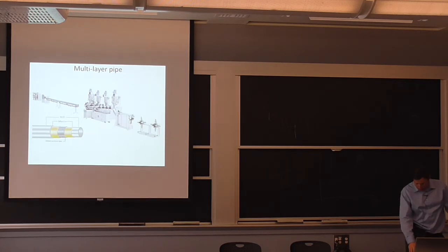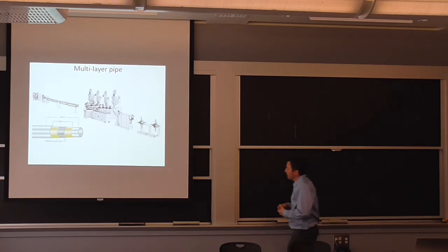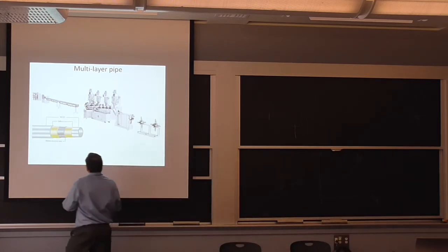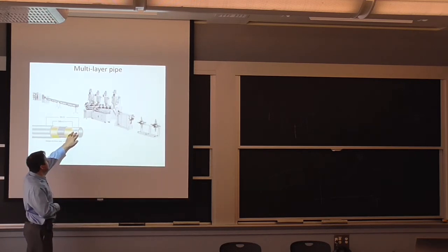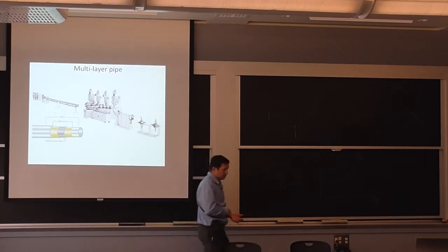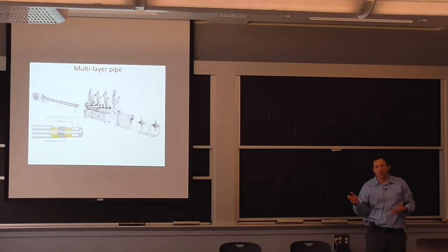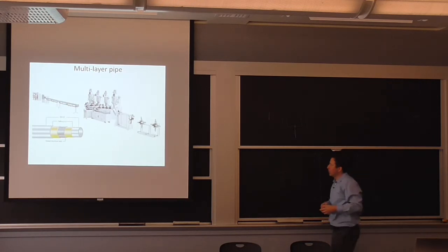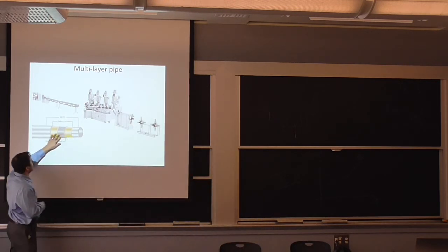I really wanted to go through this example of a special pipe that utilizes multiple layers. I think we'll have to postpone that a little bit, but the idea here is if you want to avoid having oxygen in your plumbing system, for example, that goes through a boiler, if you keep supplying oxygen into the boiler, you'll corrode the entire boiler. So you want to limit the intake of oxygen. And plastic doesn't do that, so this specific system has multiple layers.